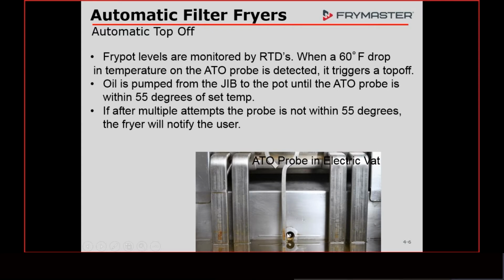That's why if we had debris in here, the oil would be coming up and it doesn't go inside there, it's going to pass that. Eventually it's going to get up to temperature, but it's going to slow the response down, which means we're going to top off too much. Is that a service call? We have had many service calls on that very thing right there.